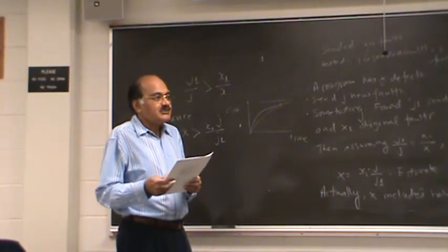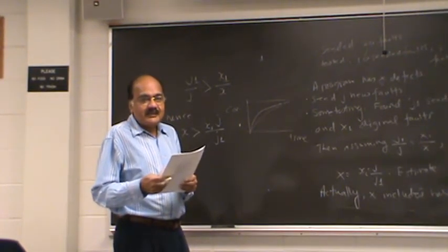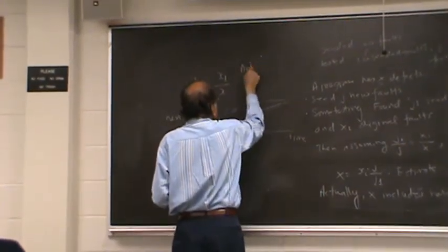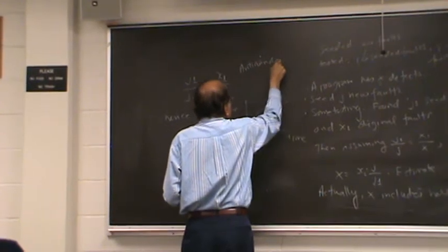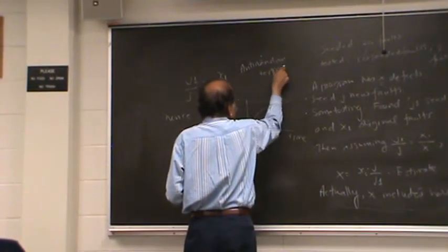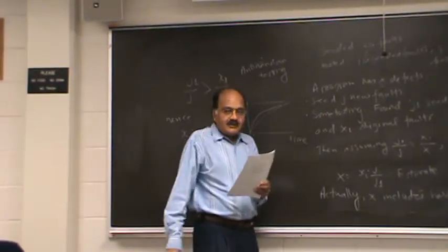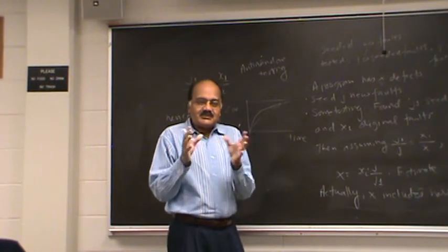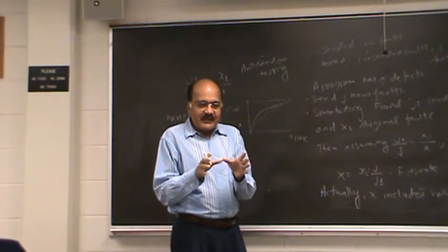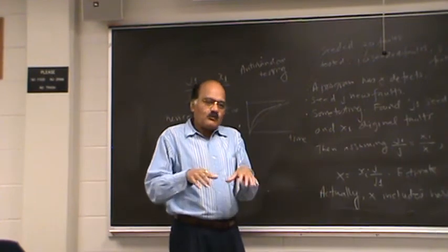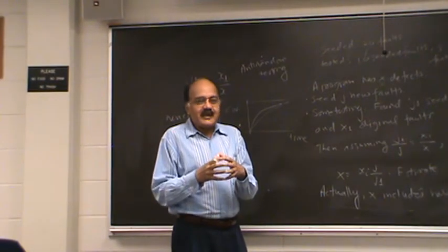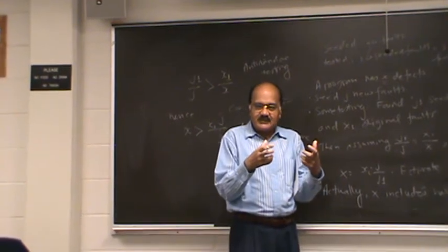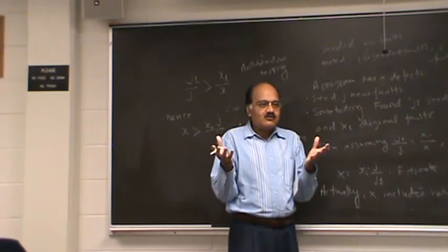We proposed a scheme called anti-random testing. In anti-random testing, maybe I will talk about that sometime. That is an idea that we struggled with for quite a while. So the idea is that each test applied is as different as possible from all the tests applied before. And the idea is that this way, every test has the best possibility of detecting additional faults.